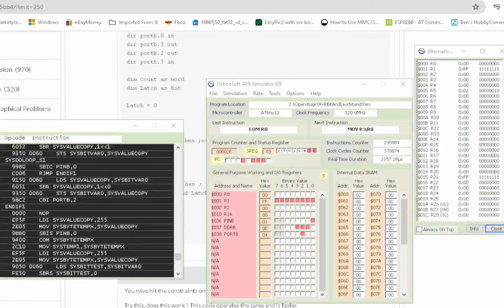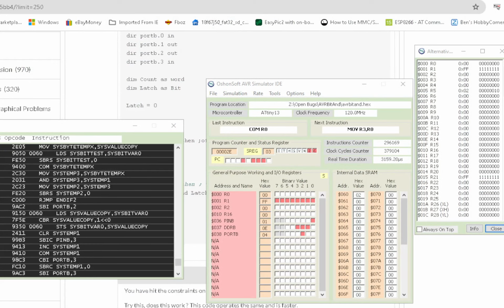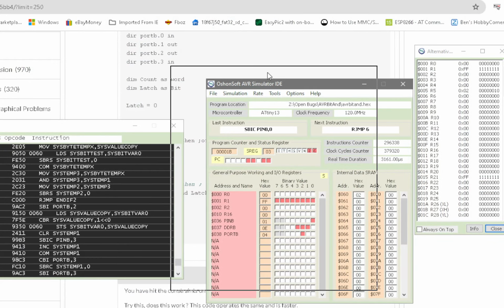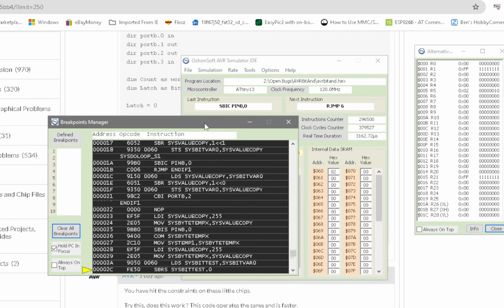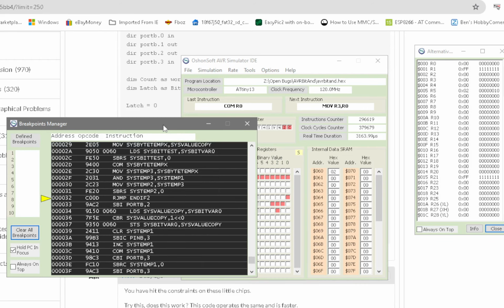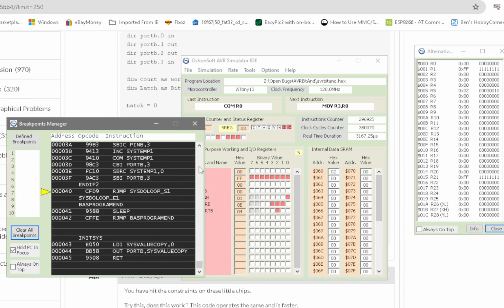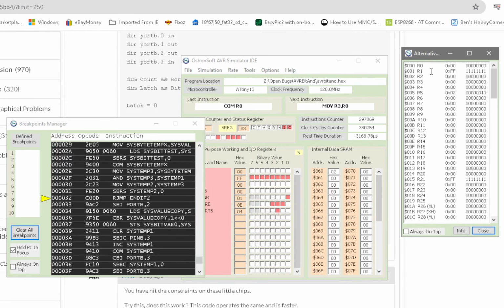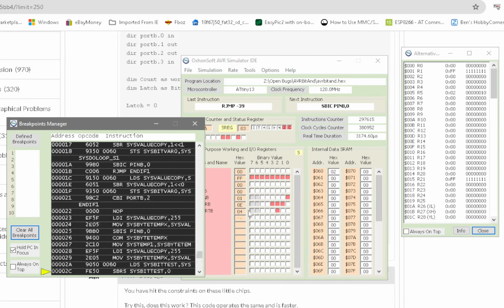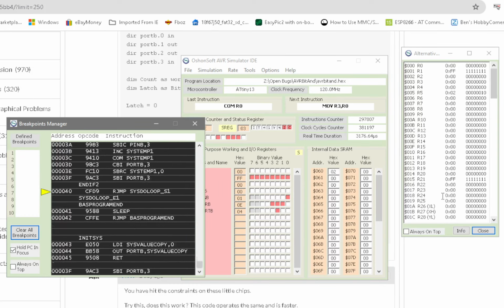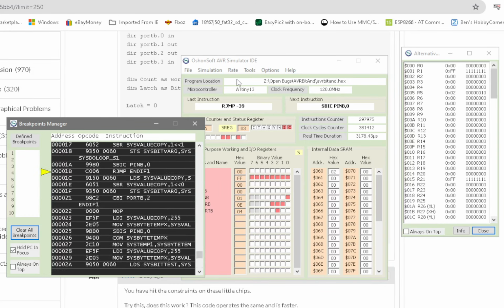So it's working now because I've fixed the compiler. Okay, all right. So what we've got here on the screen is the actual integrated circuit. This is the microcontroller. This is actually the listing that's running. This is the actual program that's running, and that's direct from GCBASIC. Okay. Can I make that a bit smaller? There we go. And these are some registers up here, memory registers, and these are some in the middle here, some other registers. Okay, and so these are the working registers, and up here this is an alternative view of the same registers. So let's just see what I've done back in my source code.